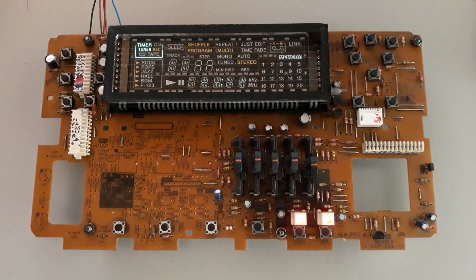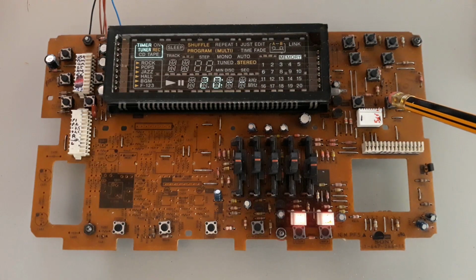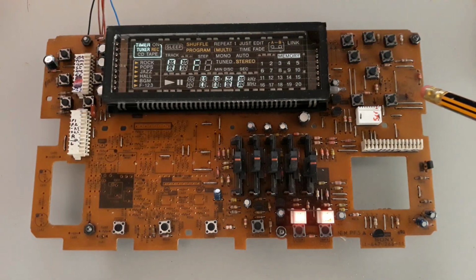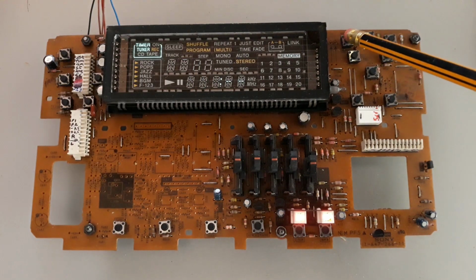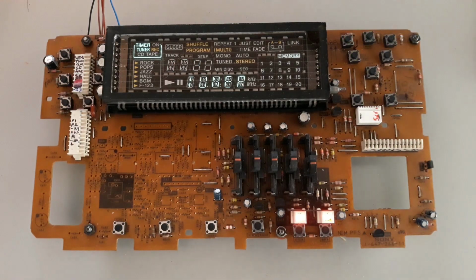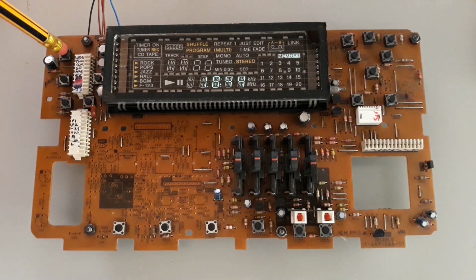The panel includes a 5-band audio equalizer circuit, based on two integrated circuits with the reference M5226FP. To make use of this section, we must provide plus 7.5 volts DC, minus 7.5 volts DC, and the corresponding analog ground reference available through connector CN502. With those supplies present, the equalizer can be reused as part of a custom audio project.